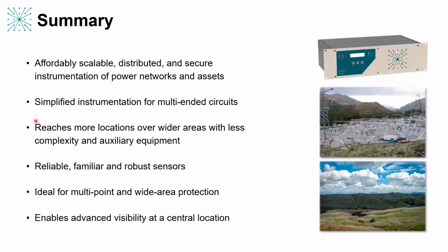Our sensors, they're optically instrumented CTs, so they're reliable and familiar to installers, and they're also very safe and quick to install. All of which makes the technology ideal for multi-point, wide area, complex protection of power networks. And finally, beyond that protection instrumentation, the system can be upgraded with no additional hardware to deliver high quality point-on-wave measurements from that wide area to a central location, giving the operator advanced visibility of that network and supporting smarter asset management. So I hope that's been very useful for everyone.